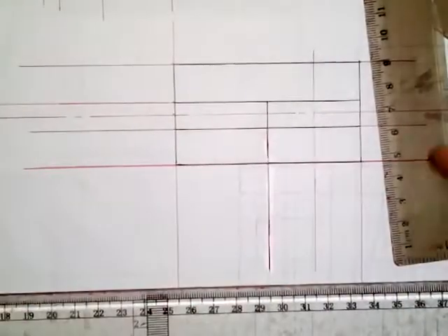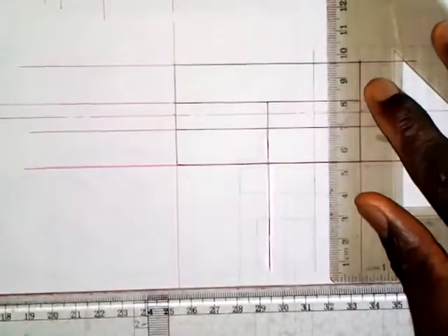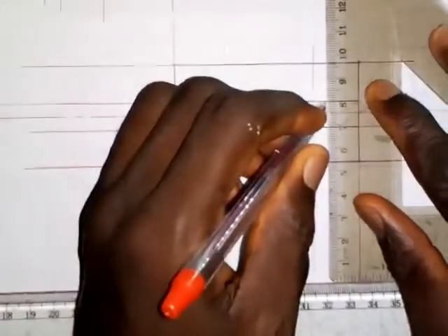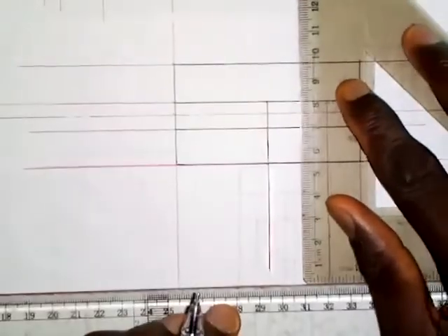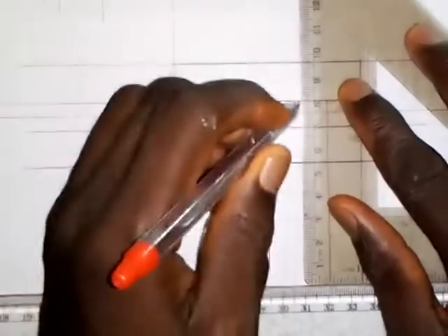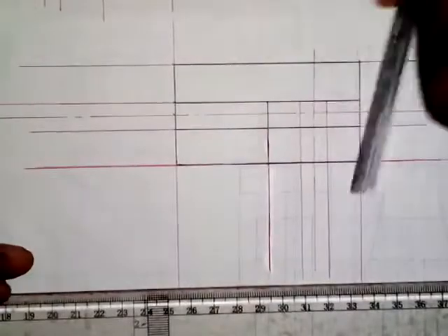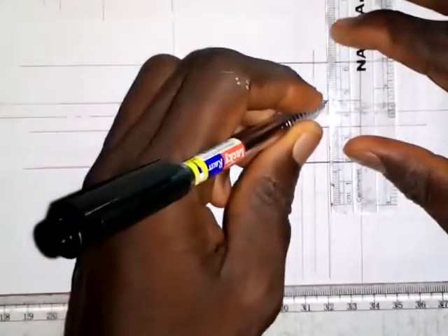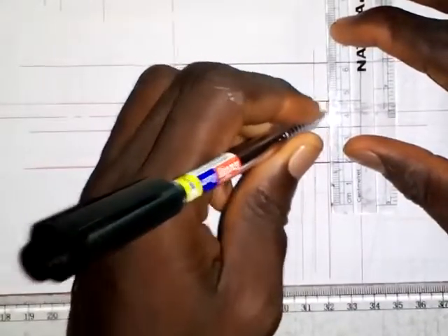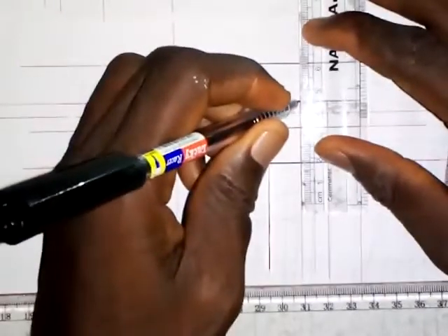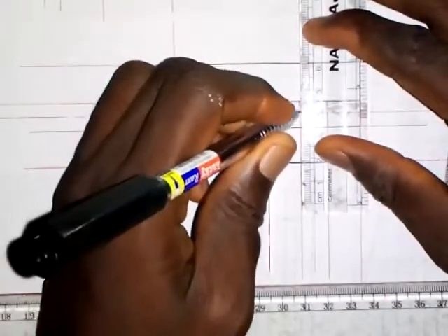So here I'm going to show it. First of all, let me draw a vertical line. Here I will draw a vertical line down, and here I will also draw a vertical line down like this. But here in the plan it will be hidden, so I'm going to draw this with a short dashes line. Here I will do the same thing, short dashes line.